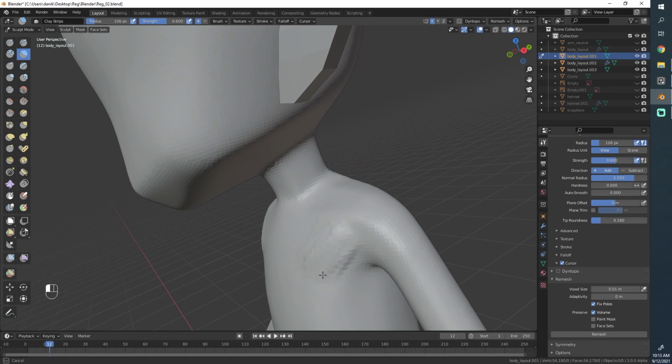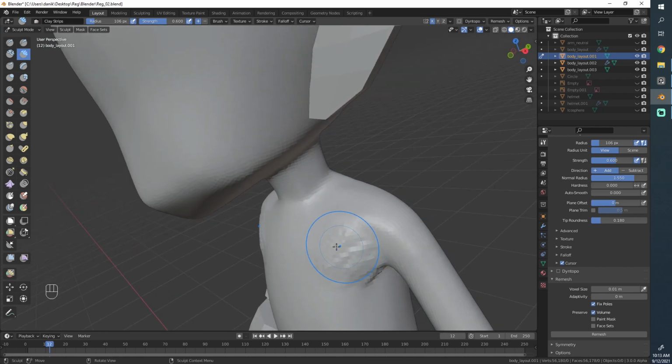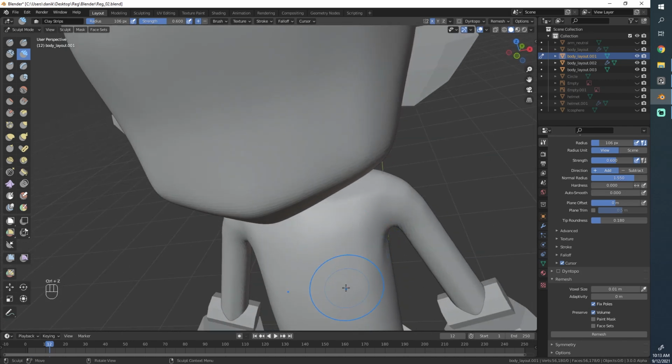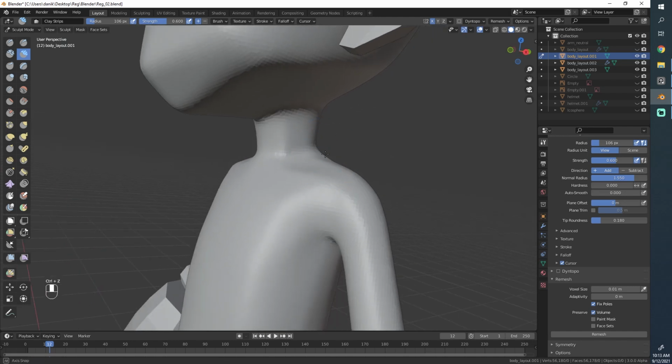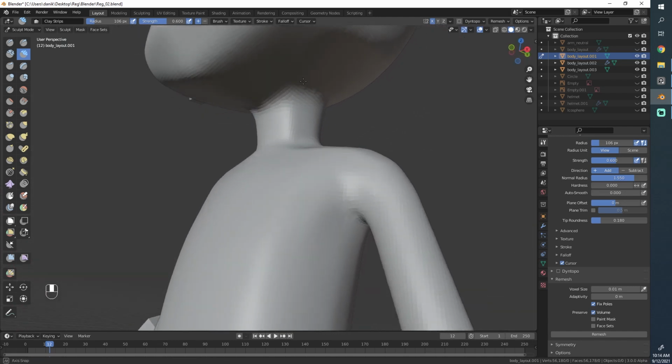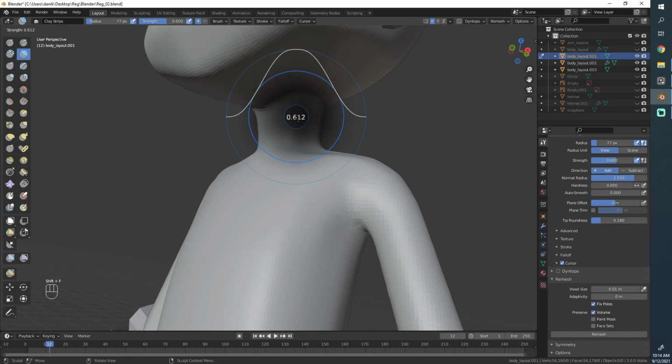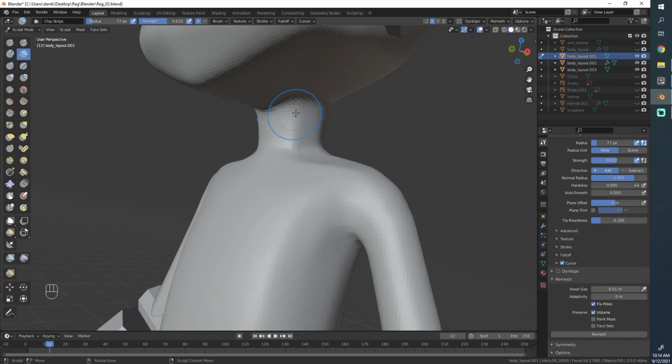If you make a normal stroke, you get, for example, here additional volume, but you can also hold Control and make a stroke, then you get sort of the inverted effect of that same brush. So in this case, this part stands out a little bit. I'll press F, by the way, to change the brush size, and you can also hit Shift F to change the opacity, but we don't need to change that at the moment.